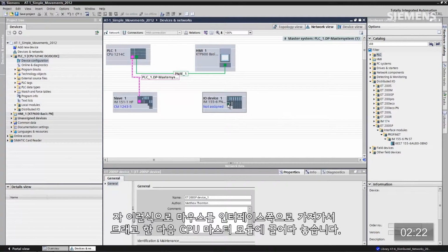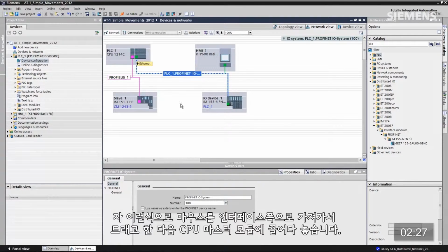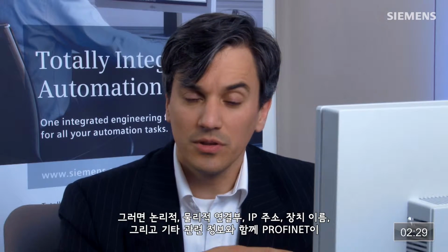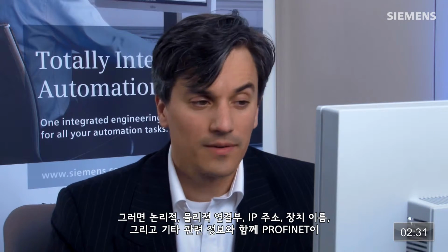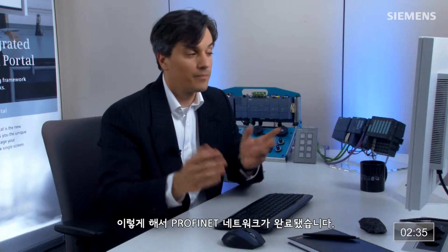How about networking this to the Profinet side of this system? Let's just mouse over the interface of it. Let's drag it onto the master module of the CPU. It auto-creates the Profinet network to the master, including logical physical connections, IP addresses, device names, everything's done in the background. The Profinet network is done as well.